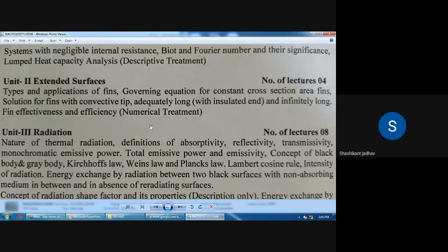We have seen an electric motor; on that electric motor there are different fins. If you look at the body of an electrical motor, it is a fin type body. So what is the meaning of this? Whatever heat is produced inside that motor, the maximum heat is dissipated into the surroundings by using those fins. We want to increase the heat transfer rate, so the electrical motor has a fin type structure. Because of that fin type structure, the maximum heat is dissipated into the surrounding.